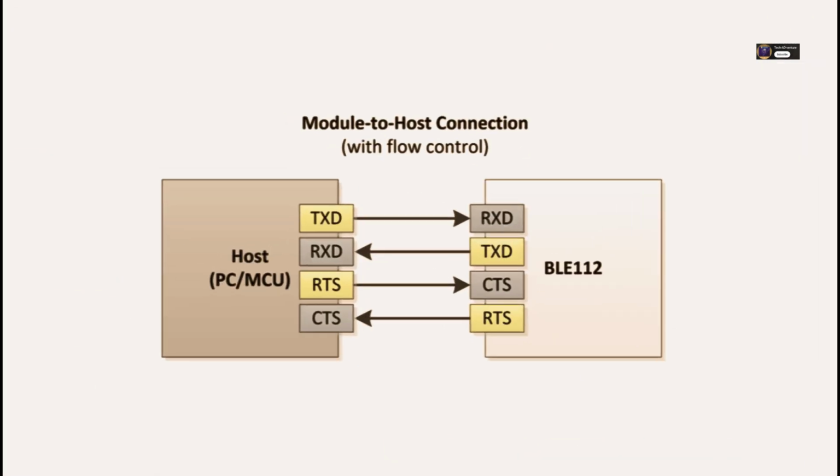Hardware flow control, RTS/CTS, is generally more robust and reliable because it's out of band, using separate wires. Software flow control, XON/XOFF, is useful when you don't have those extra pins available, but it does consume a tiny bit of bandwidth for the control characters and relies on those characters not appearing in the actual data stream, or needs escaping mechanisms. Basically, use it whenever there's a risk of the sender transmitting faster than the receiver can process, to prevent data loss and ensure stability. Makes sense.